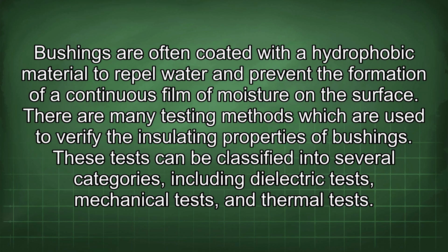Bushings are often coated with a hydrophobic material to repel water and prevent the formation of a continuous film of moisture on the surface. There are many testing methods which are used to verify the insulating properties of bushings. These tests can be classified into several categories, including dielectric tests, mechanical tests, and thermal tests.